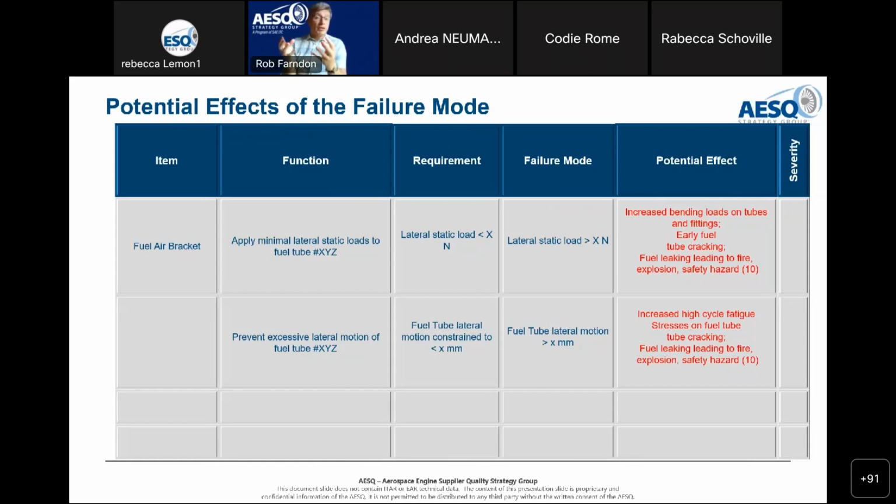It'd be important to other teams who are taking your DFMEA and potentially using it to make allowance for the effects in their design. Some templates in some companies, and I know Rolls-Royce does this one, divide the potential effects column into component, subsystem, and system, just to try and provide an indication where different teams might need to be